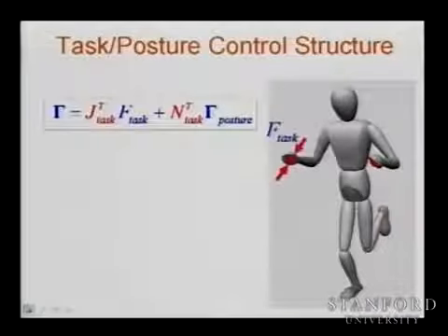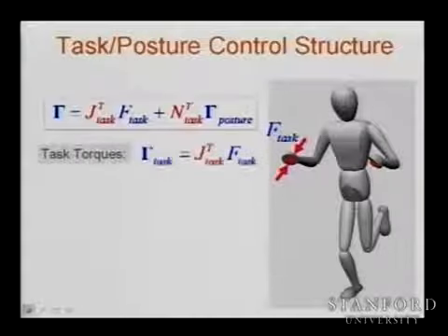It's very easy. We use the energy, that is, we use a force of task to control it with J transpose F. But now, suppose I'm controlling the legs and the hands, but I have all this motion that is possible. This is the null space motion. This is what we will discuss with redundancy next quarter.